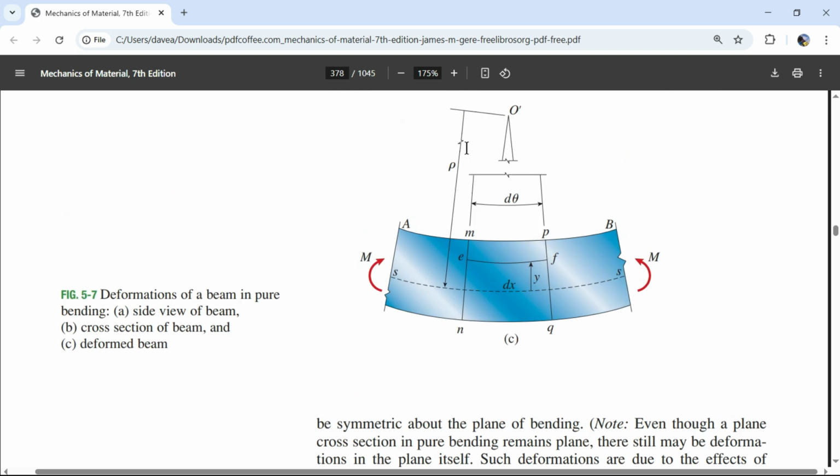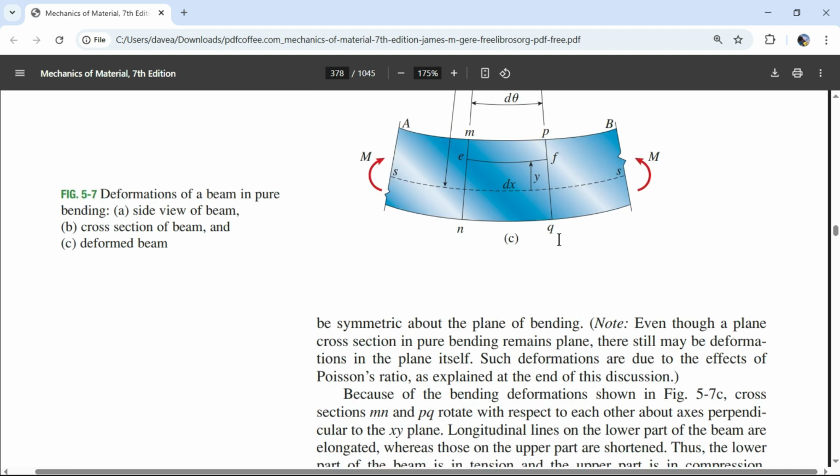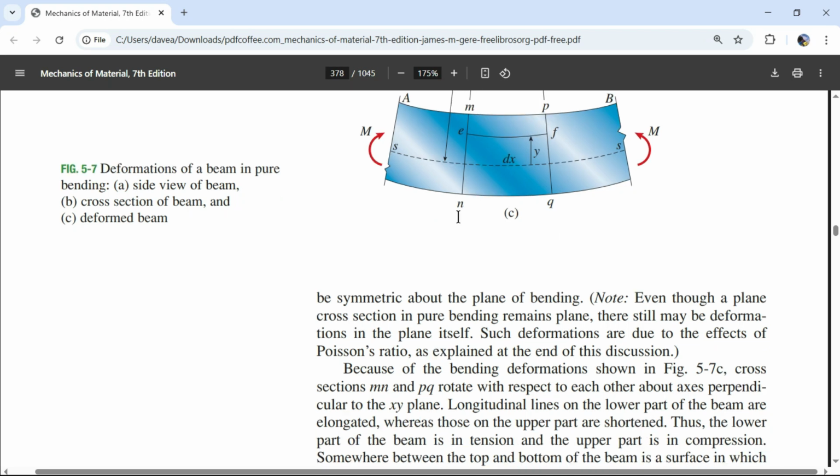But that's why I definitely like to go back. I think it's very useful to put 4 steel atoms, and this moment has to be a load. It has to be 2 opposing forces, and if I just have 4 steel atoms, the forces can only be axial through those atoms, that's the only place that I could put a force, at the center of mass of those atoms. So there you go. I got a compression force on the top 2 and then a tension force on the bottom 2. And so that's a great way to explain why these lines are now slanted.